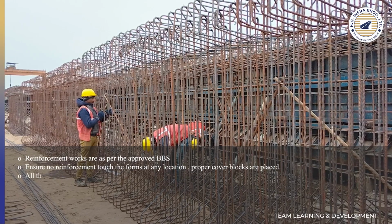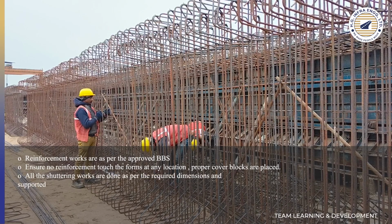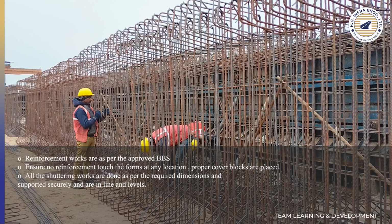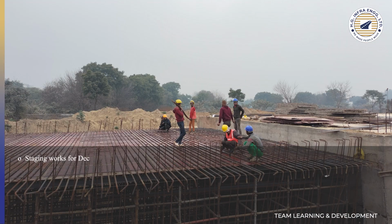Proper cover blocks are placed. All the shuttering works are done as per the required dimension and supported securely and are in line and level. Staging works for decks are as per the approved design. In short, approved shuttering oil is used at the time of fixing of formwork.